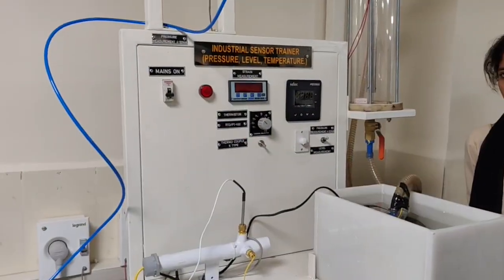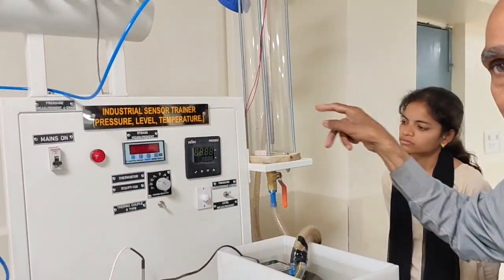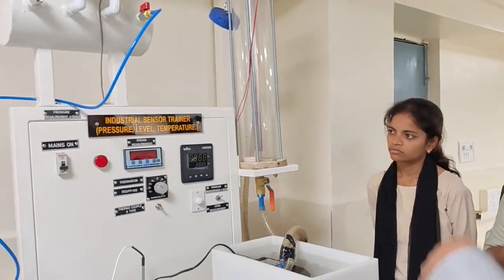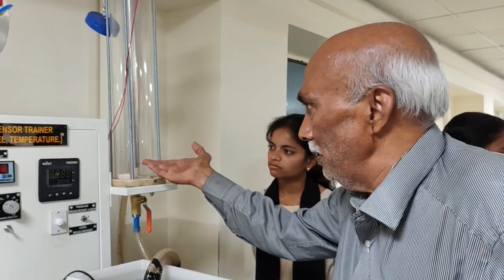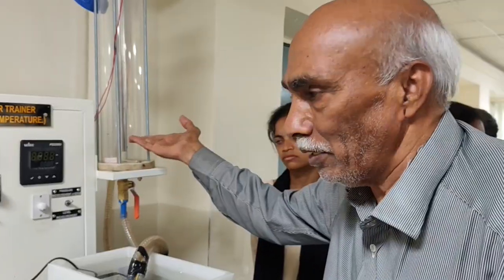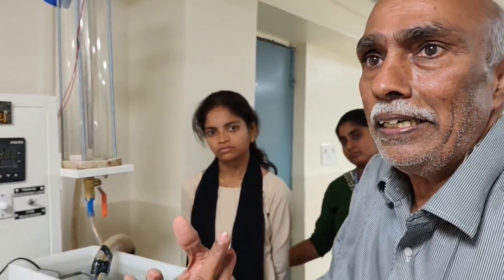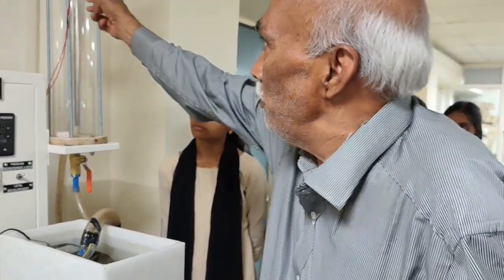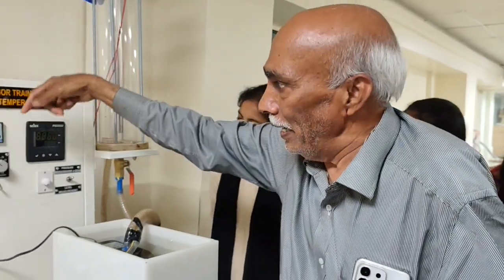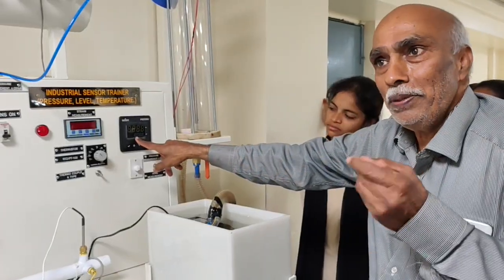Capacitive is also there, sir, actually. Capacitance is there. This is a glass tube. Whatever inside rod is there, that is a capacitance. For that a drawing is there, I will show you the drawing also, how we measure inside, the construction, everything. See, once any fluid or any material, even solid material, comes in contact with that, it moves up and down, and some voltage will be developed. That voltage will be taken into this wire and connected to the meter. That voltage is measured.